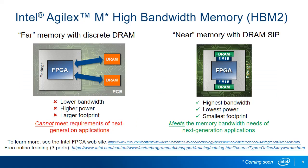One other option for external memory is high bandwidth memory. High bandwidth memory, or HBM, is currently in its second generation as a JEDEC standard. HBM2 uses through-silicon vias, or TSV, to connect up multiple memory die layers into a 3D stack. An HBM2 stack can provide up to 256 gigabytes per second bandwidth and run with clock speeds up to 1 gigahertz. Like external DDR, it uses a wide, parallel interface of 1024 bits, where each I/O provides up to 2 gigabits per second. Because of the large number of parallel signals required, HBM2 is implemented in an integrated device that includes the memory controller.